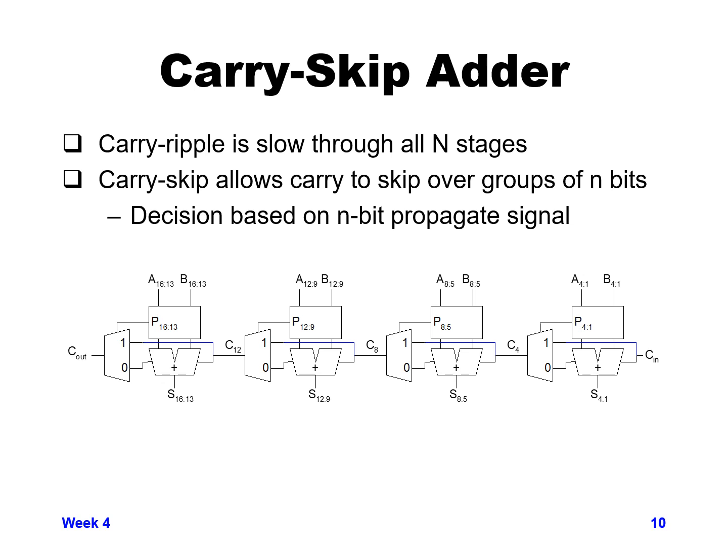So you can see as the carry is going through, the carry is only going through a single delay element for every 4 bits instead of a single delay element for every bit. And so this can actually reduce your delay through the full 16 bits by a fairly decent factor, and we'll look at that in the next foil.